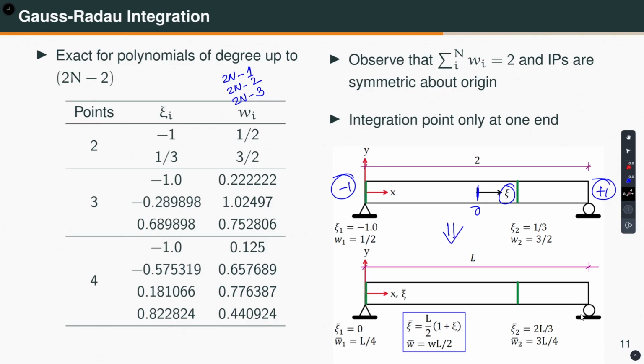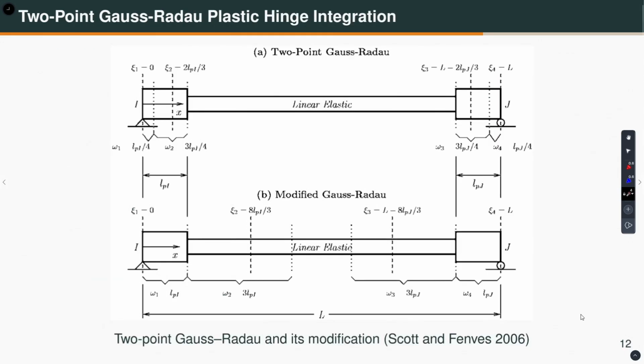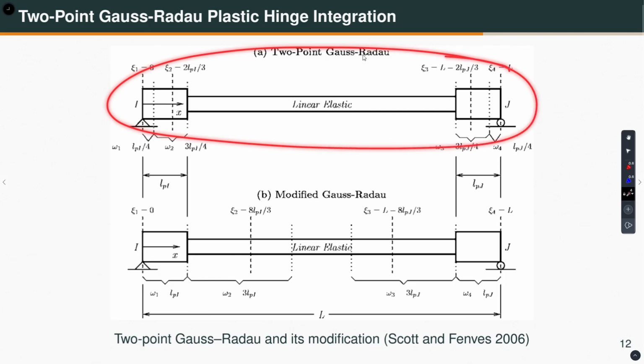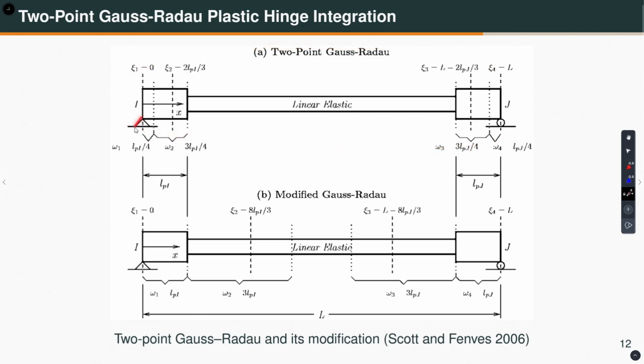Okay. Now, with that, let us say this is your element, in the simply supported basic or deformation system, right. And we are saying that this part is my plastic hinge, for which I am getting the hinge length from empirical equations. Let us say this length I am calling LPI and this length I am calling LPJ. This is element end I, this is element end J, right.